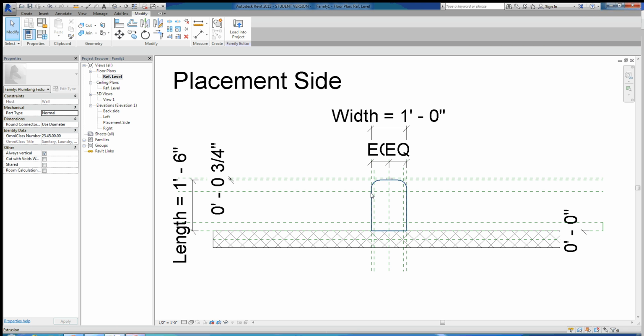So now that we've done that, we want to make sure that all of these dimensions are locked as well. We want to make it so that we're always 4 inches down from that end wall there, we're always an inch inward from that wall, an inch inward from that wall, and we're 3 inches inward from there. It'll just make it so the walls will always stay the same, and the void inside will grow or shrink.